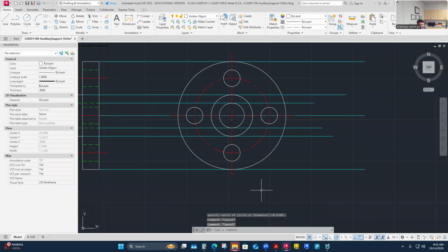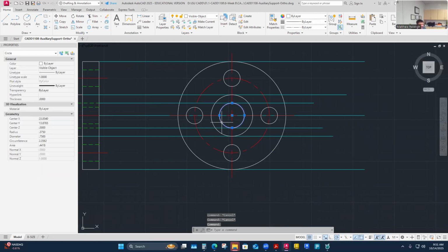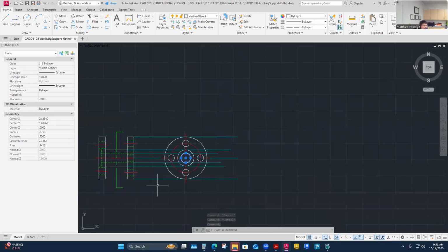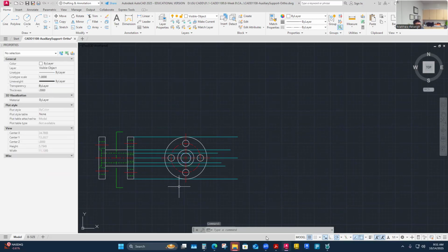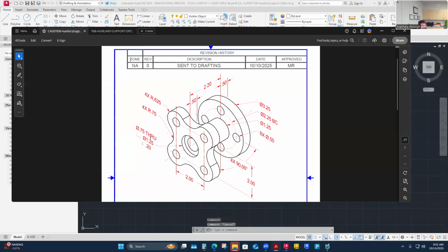And that should be the 0.75 diameter that was through. Like it was really called out in the counterbore that it went through. Maybe it should have said through all, would have been helpful, whether it's just through that plate. So I can argue a little bit from a drafter standpoint. Through could be interpreted as through one plate. Through all is even more descriptive, and that means through everything, all through all plates. So I could argue that this should maybe say through all. The way I've drawn it is through all.